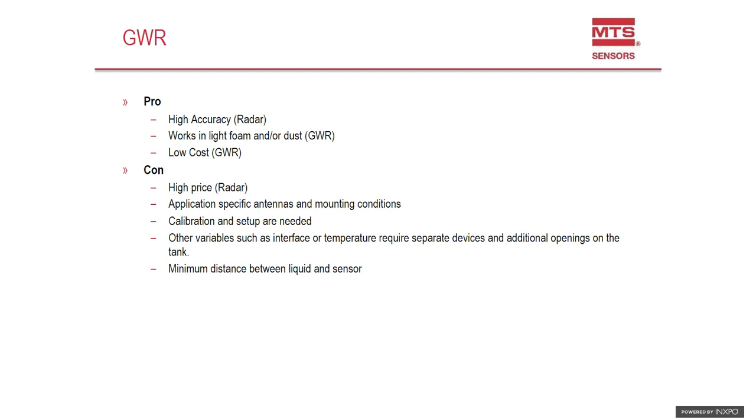The other con would be that you're not able to measure the temperature because it's not included with that device. And then also with the guided wave radars, you do have a blanking distance at the top and bottom of the tank.